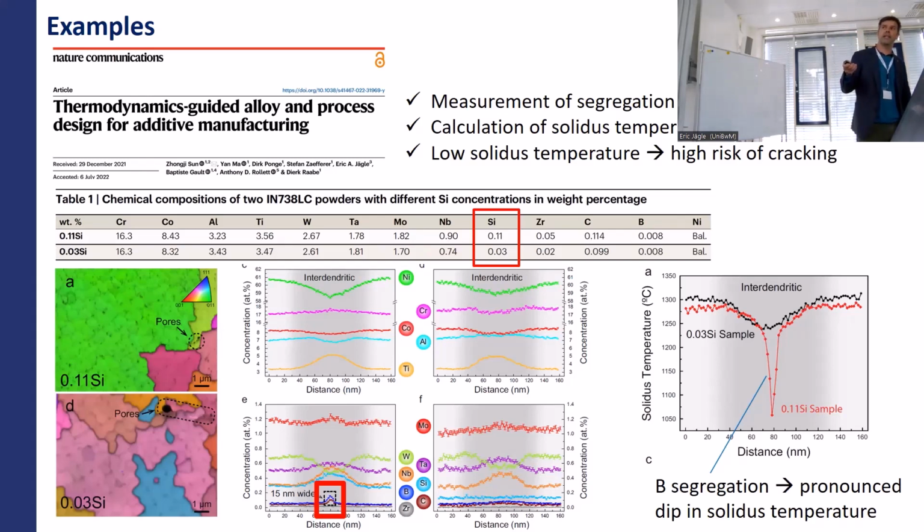So I think here you see the cells sort of pointing out towards you, and you see this segregation around the cells, and you also see everything happens at a very small length scale. And yeah, they had access to very nice experimental equipment, atom probe tomography. Not everybody has this, and they were able to measure the segregation between these growing cells or dendrites.